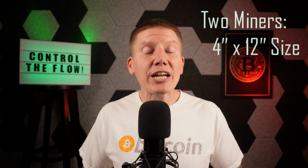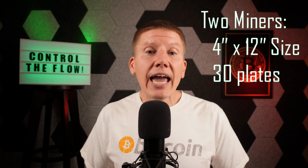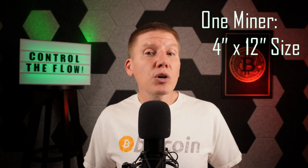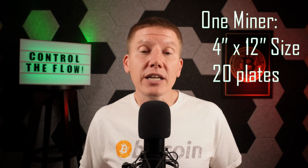Now, I've played with some of these design calculators and done a few back of the envelope calculations myself, making some assumptions along the way, and in general, here are some guidelines to work from. For a two miner setup, if you're looking at a 4-inch by 12-inch heat exchanger, you'll be looking at maybe a 30 plate design. And for a one miner setup, again, a 4-inch by 12-inch heat exchanger, you'll be looking for something like a 20 plate design.